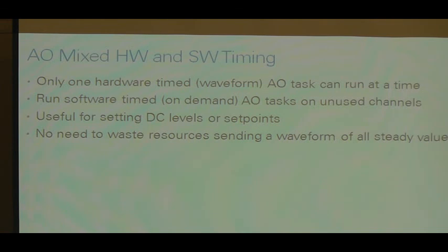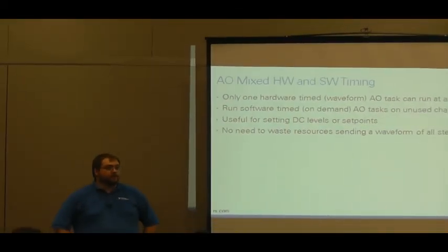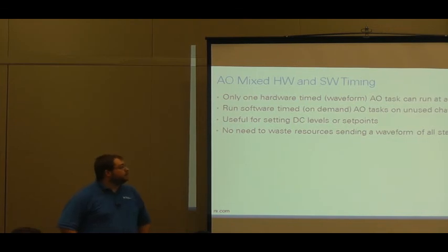What I can do, though, is while that's running, I can do a software timed task on any of the other channels. So while I'm clocking out a sine wave on AO0, I can use an on-demand or software-timed DAQmx task to update the values of my other channels. This is useful for when some of your channels are a waveform, but other channels are just a DC level or a slowly changing set point, where the exact time that transitions isn't as important. We can use the software timed task to update those levels.